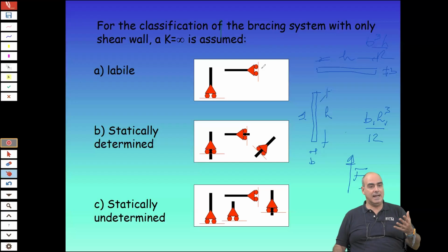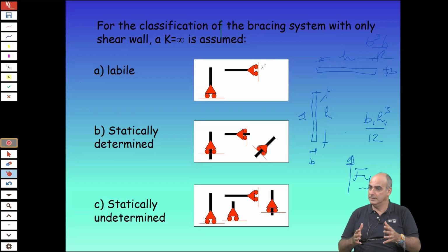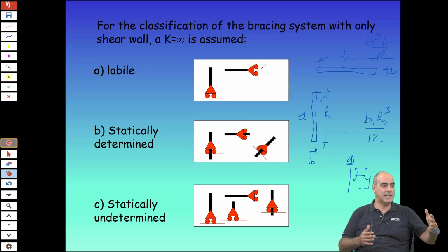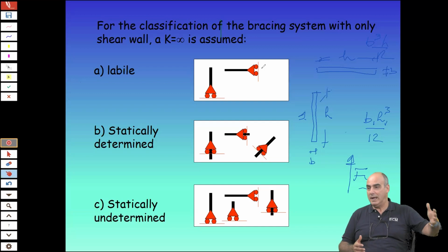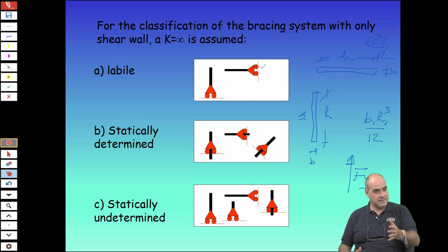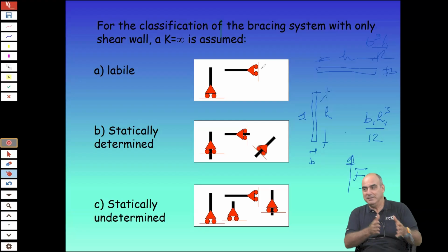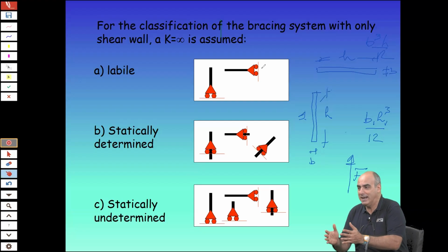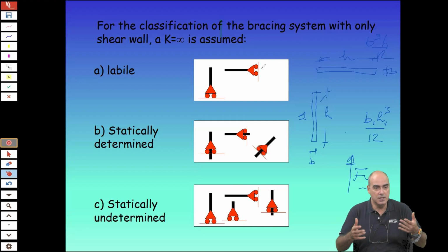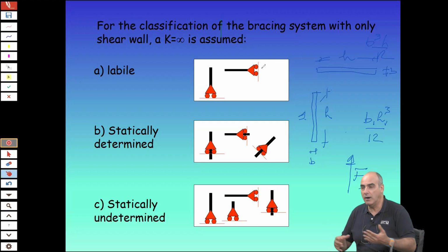So we hypothesized that some elements could experience some corrosion. And which were the elements experiencing corrosion? Well, we said the wind comes from here, so the first elements to corrode will be the ones windward, and then progressively. Well, we observed that as long as the corrosion starts progressing, the corroded elements gave back some of their initial shares of the moments, of shear and so on, to the other elements.